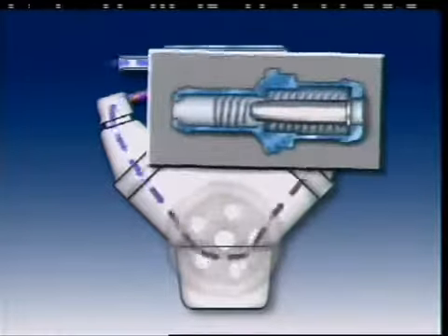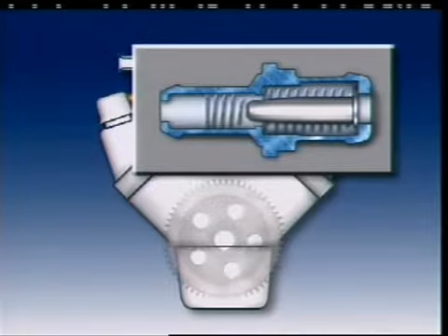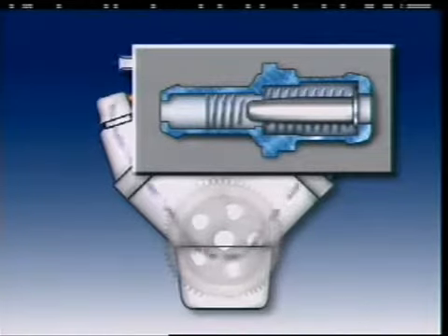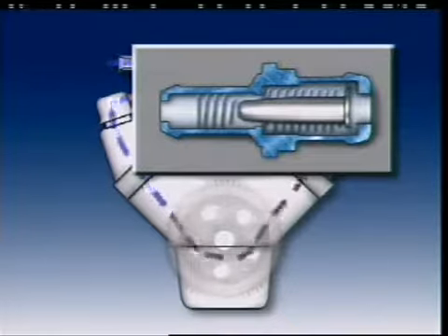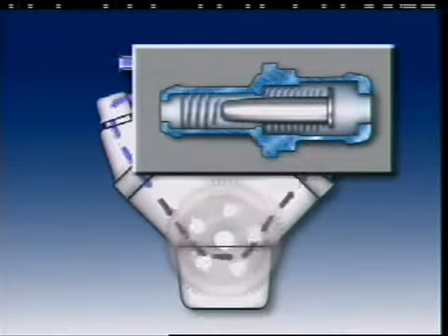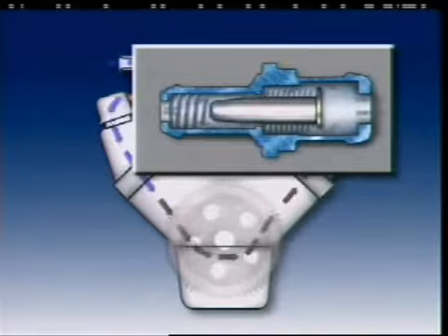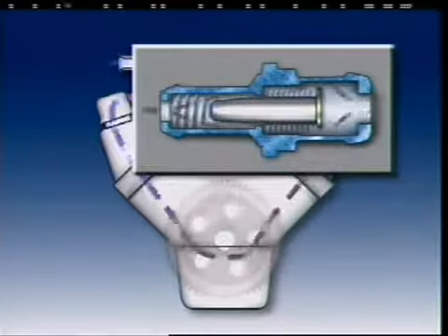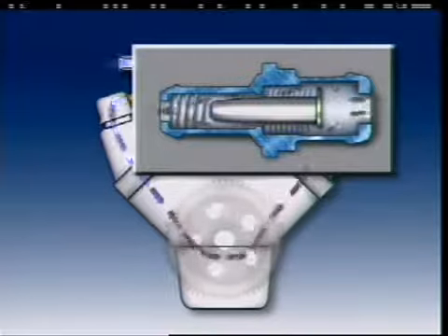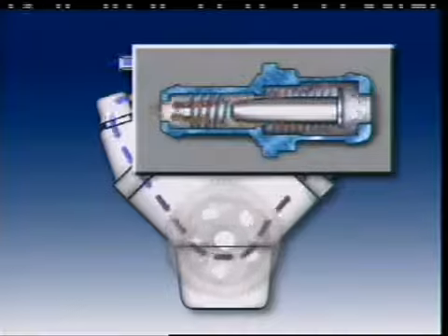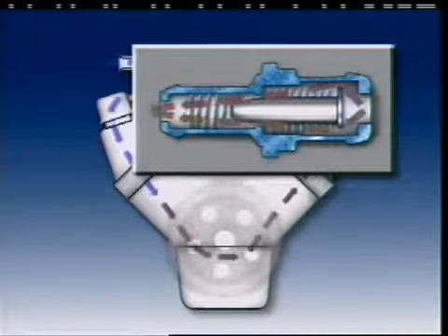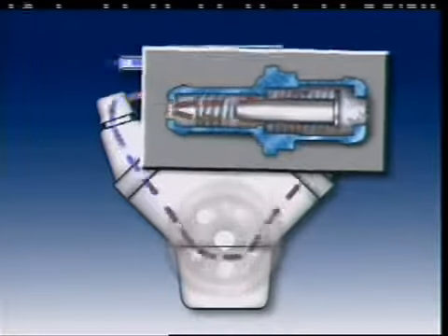It is controlled by the pressure in the manifold. With the engine off, the valve is closed and air cannot enter the inlet manifold. This allows the engine to start. At idle, low pressure in the manifold draws the valve to the other end of the body. This lets a small, measured amount of vapour pass the valve. At wider throttle openings, the valve plunger position allows maximum flow through the body, which gives maximum crankcase ventilation.